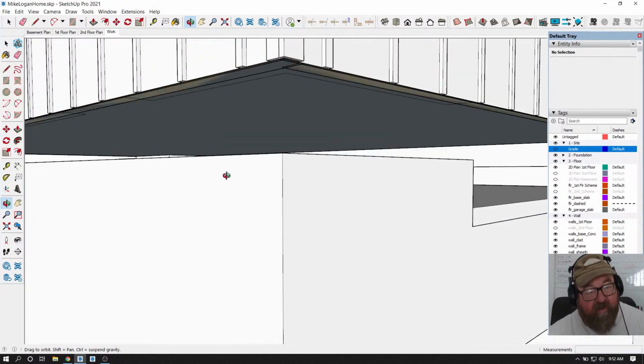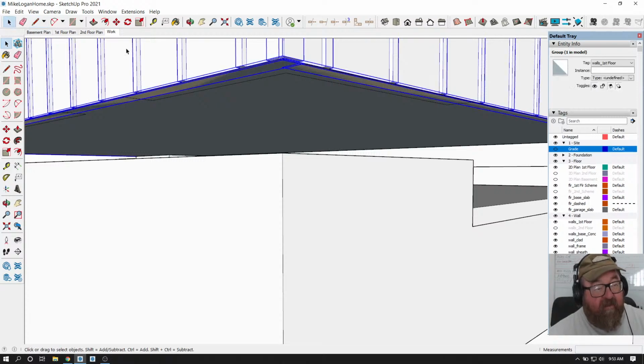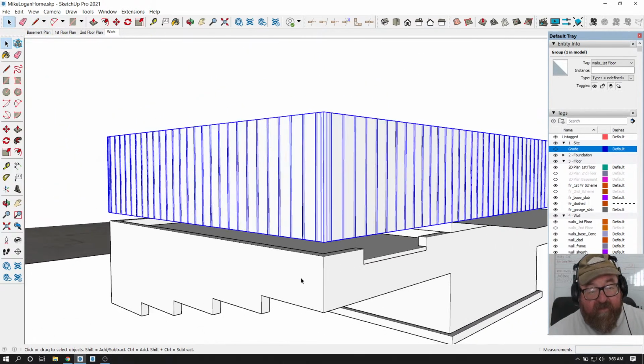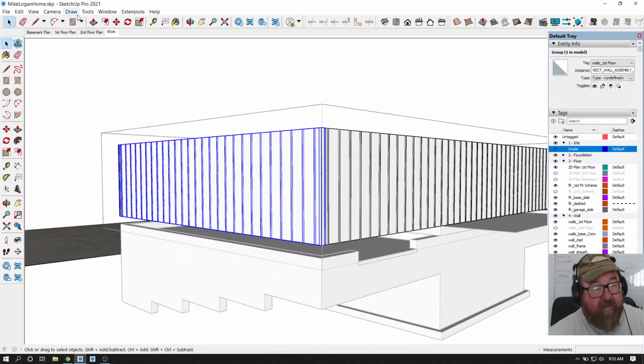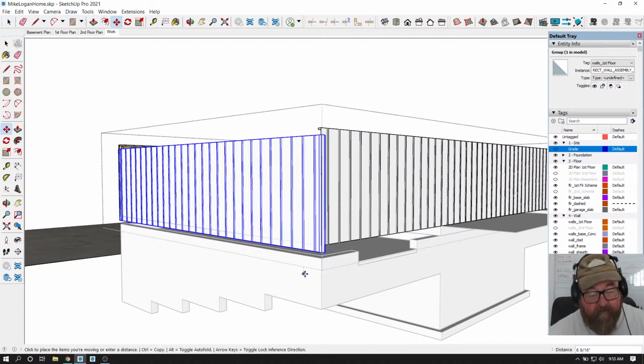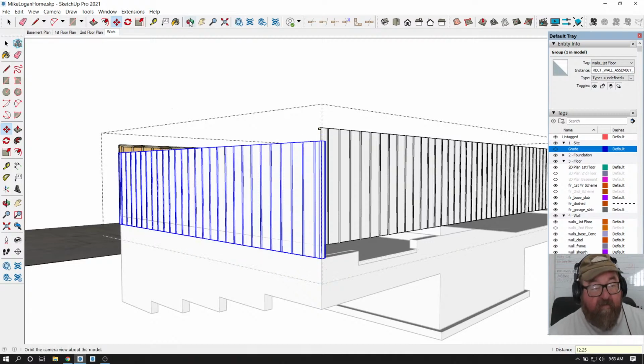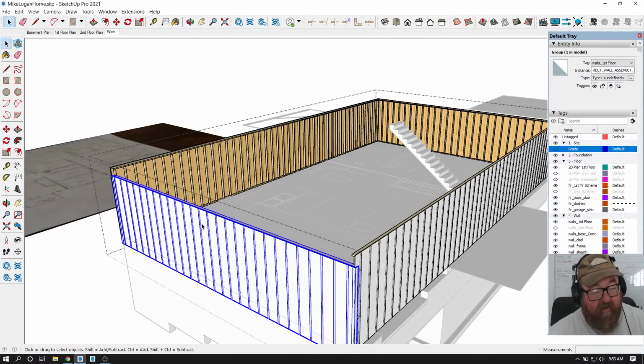And I'm going to try to see if I can just regenerate the wall after I. So that's 12 1/4 inches. That makes sense. That's how thick the floor system is. So I'm going to take this wall and move it down 12.25, and then I'm going to make it that much taller.